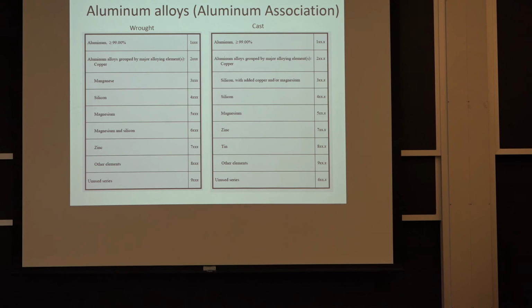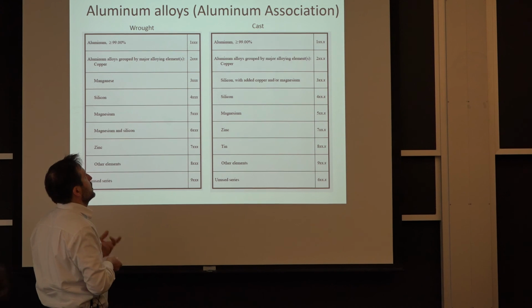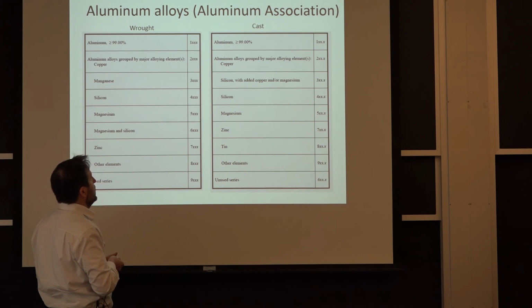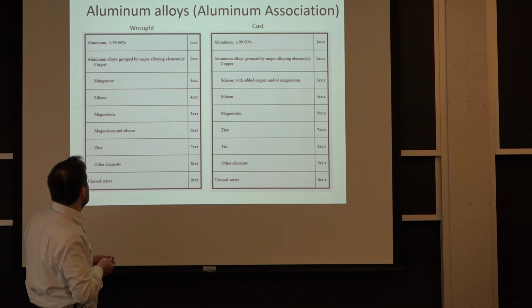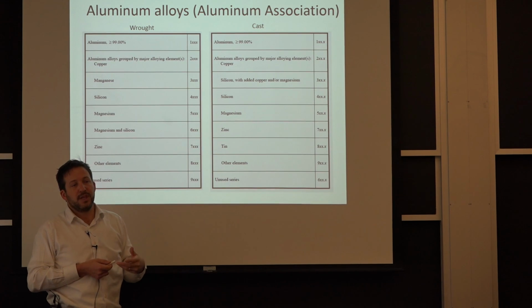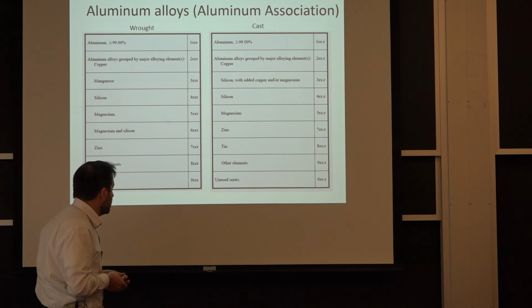Aluminum is a little bit the same story where you have a 4-digit number originally from the Aluminum Association that tells you a little bit what's in the alloy. The reason we have so many is that pure aluminum has application for conductivity, so power lines, for example. The 2000 series is heat treated, so it will build up strength by a special quenching and aging process. When you do 3000, 5000 series, those are work hardened. So the real way to get a better strength of that aluminum is to roll it cold to get it harder and with a greater yield strength.